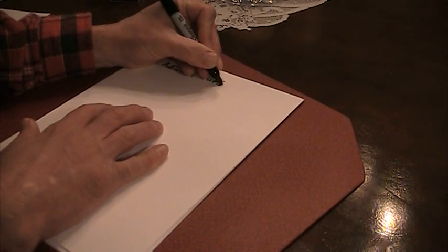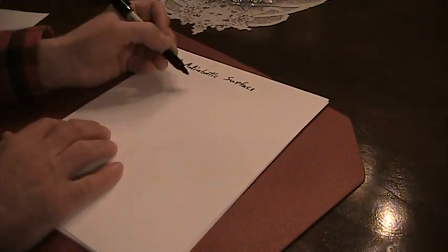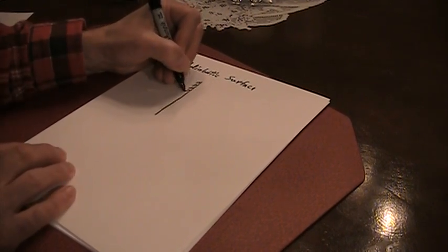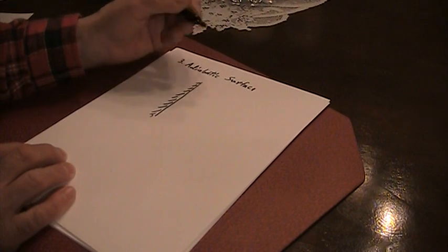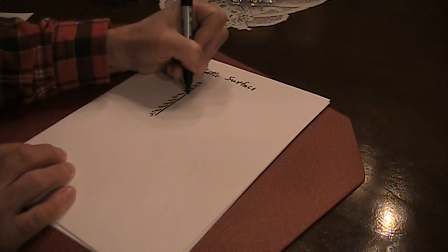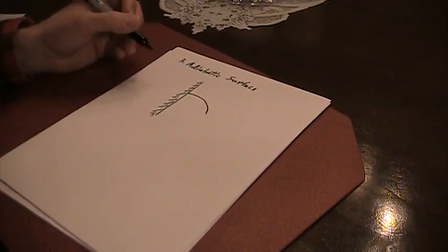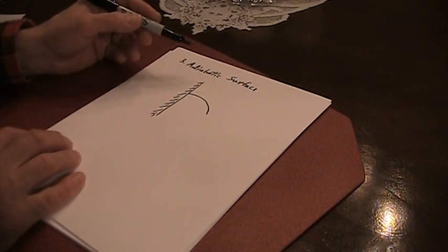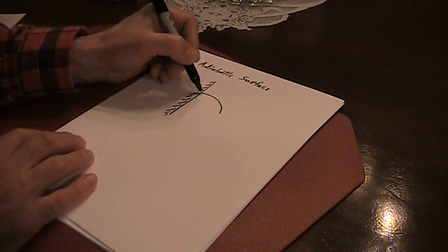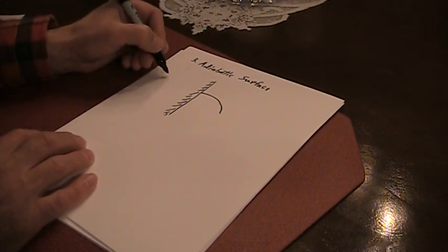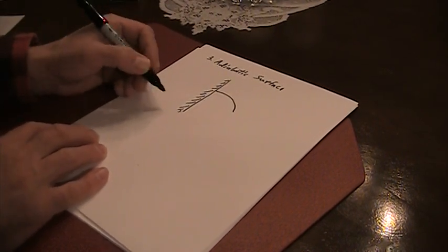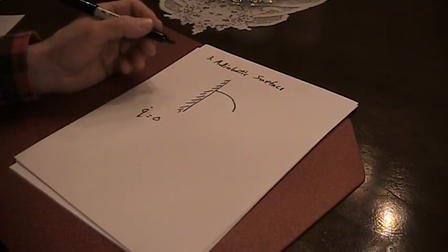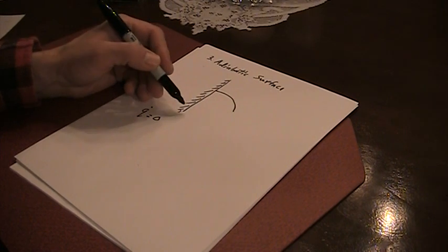A third boundary condition that you might have would be adiabatic surface. In other words, of course, you know from thermo, adiabatic means that this surface is insulated. The temperature profile might do something like this, where if there's no heat transfer going into the surface, what that means is Q dot is equal to 0 at the surface at X equals 0, right?